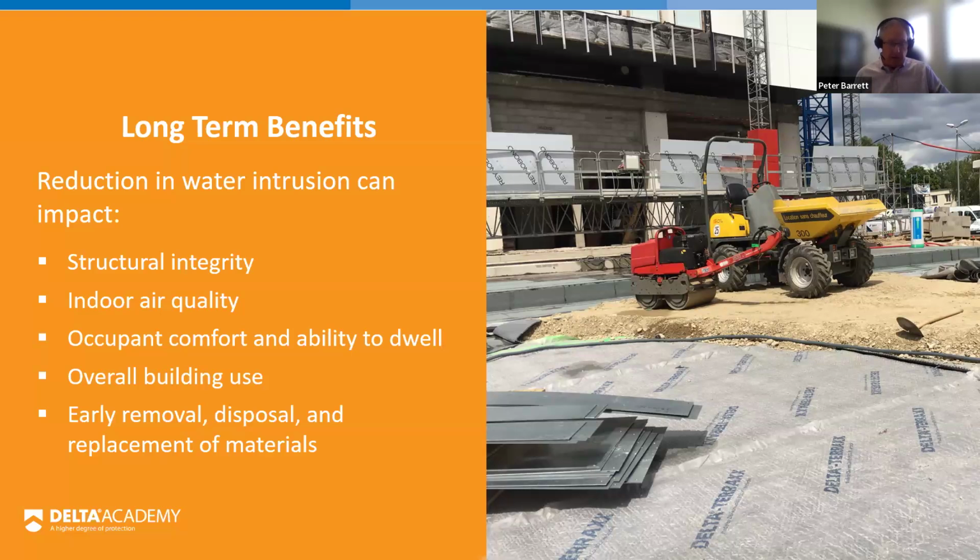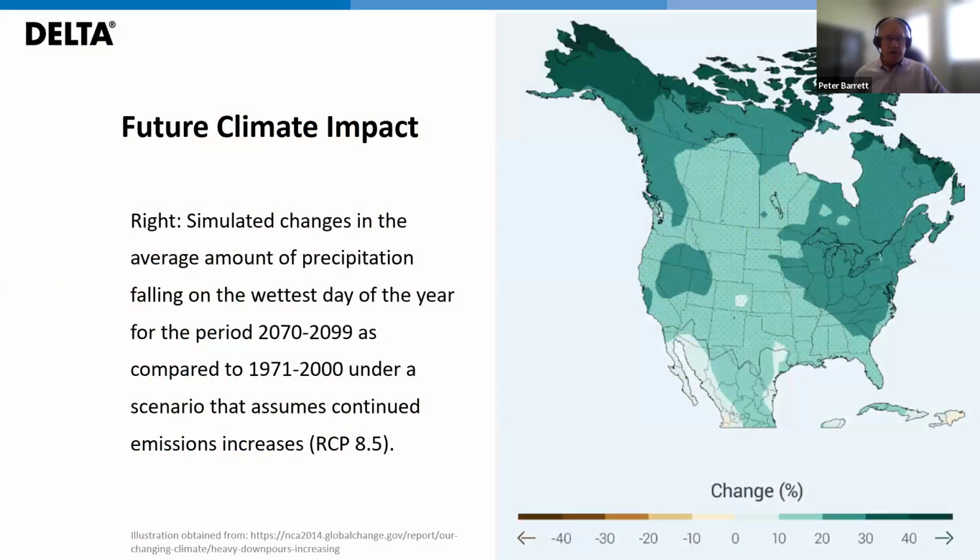No product installation can be perfect. Water might still get in, but by having good drainage, you can minimize the amount of potential water that can get in. This will take most of the water away from your actual waterproofing, and it will mean that your waterproofing has less water to manage itself. But this is also going to change in the future.